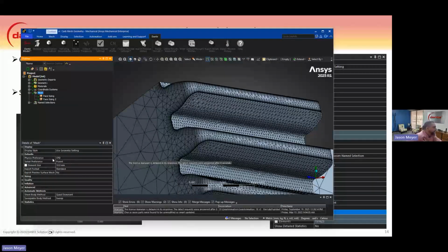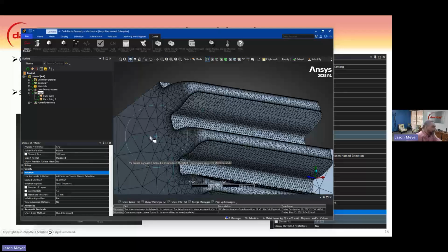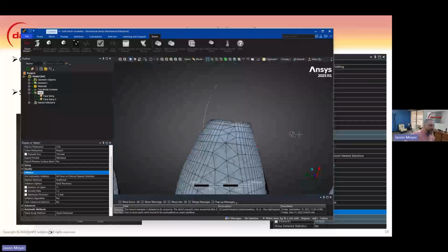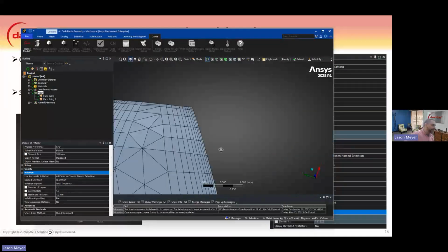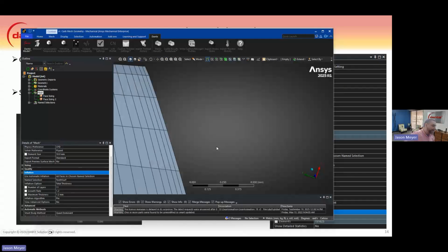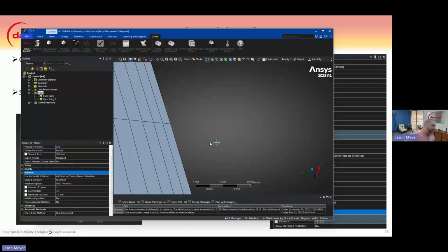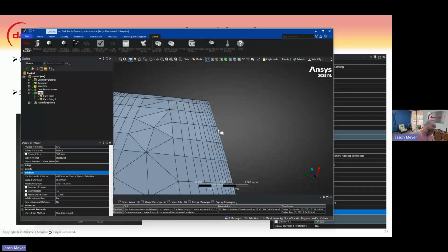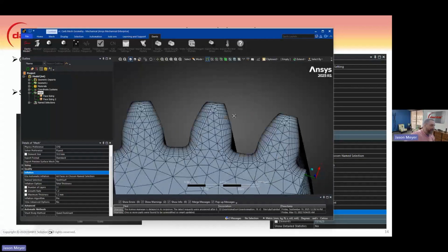What we like to use a CFD physics reference for when we develop these is that it has the advantage of having an inflation layer. Here I used 11 layers with a total thickness of 1.2 millimeters. There's a growth rate where the surface element is very small, and then it grows from there about 1.2 times each. If we zoom in on that element, we can see it is within the range of about 0.2 millimeters. We have to go really far in to see it, and then it gets bigger as it goes through. This will help capture the steep gradient and make sure we're pretty accurate.